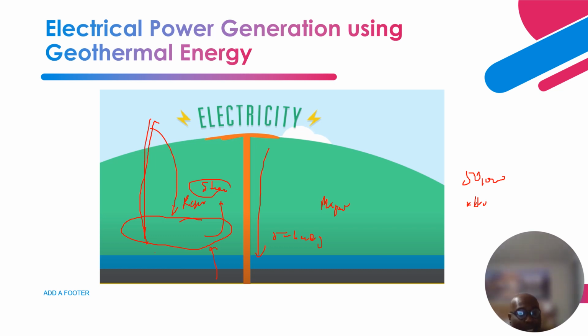And this steam has the opportunity to flow. Though it travels 5 to 6 miles through this pipe, definitely the pressure is going to drop. So as it gets here, you can have high pressure steam come out and be piped. It can go through a couple of reheats to make it a little bit drier before it gets into the steam turbine.